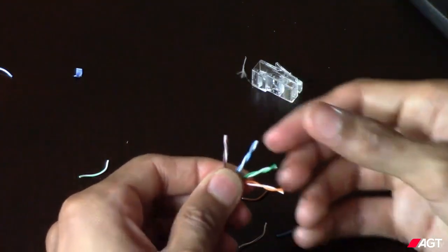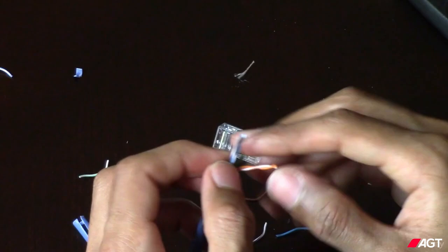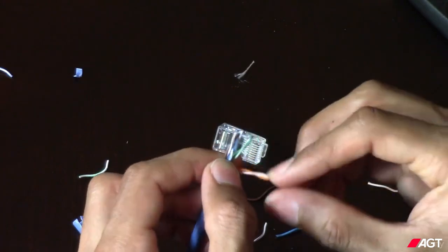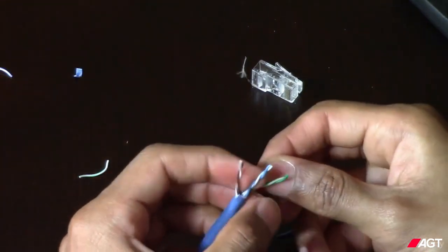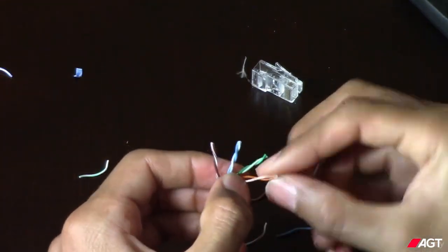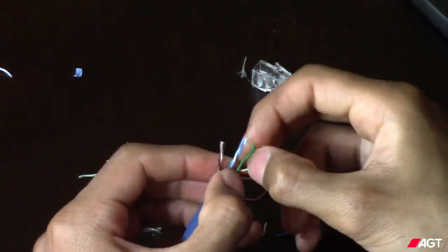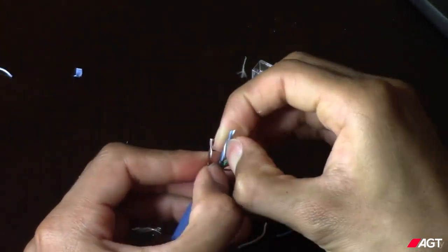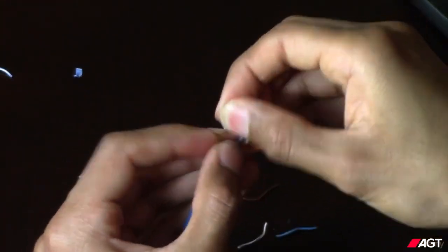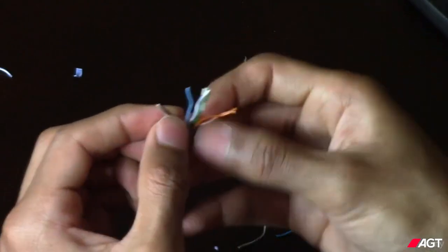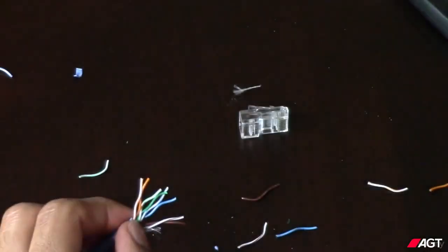A lot of this will go much faster when you've done it a few times. Eventually, you won't even need to measure using RJ45 connectors. You'll be able to eyeball them easily. Okay, now that we have access to our inner wires, we'll want to start untwisting them. Now that we're looking at a neat 8 wires, our next task is to arrange them properly by color code.